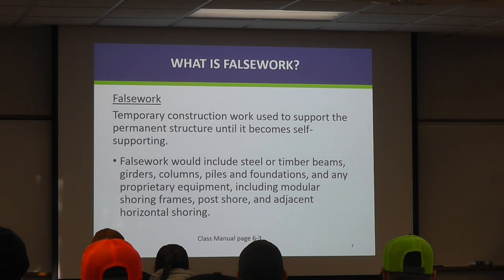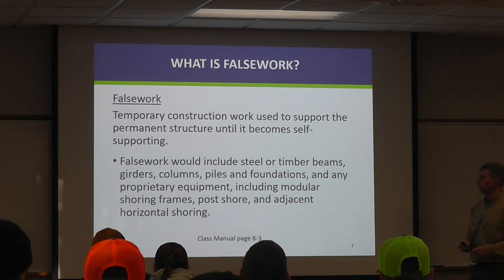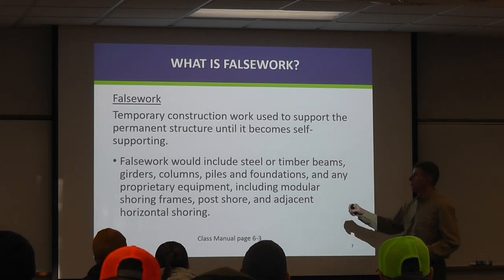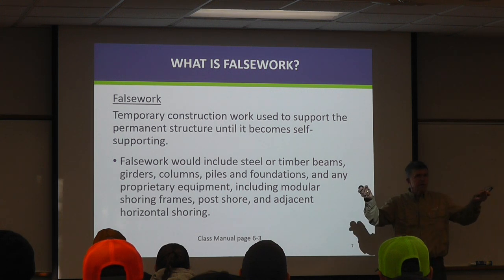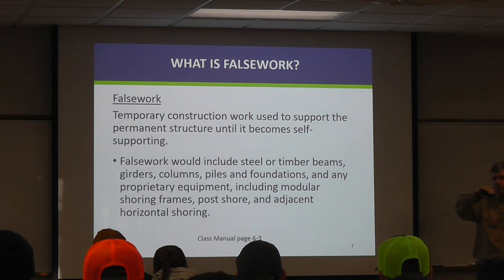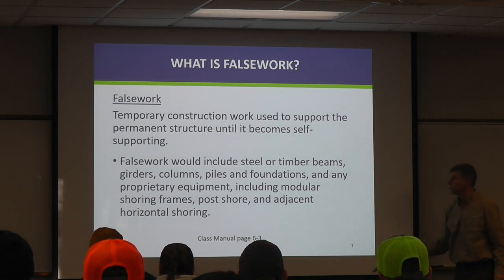So that's forms. What about falsework? I've been throwing around the terms forms and falsework. Falsework is a little bit different than forms. Sometimes they're the same. We're going to see that like on pier caps. But falsework is something that's underneath all of this load, and it's keeping whatever load is getting constructed in the proper orientation until the concrete is cured and is adequate to withstand the load.